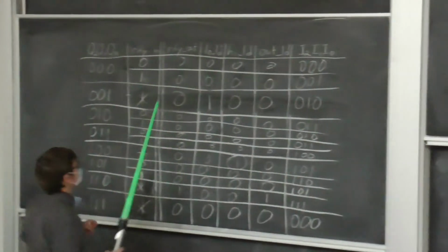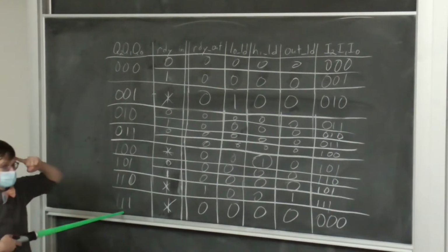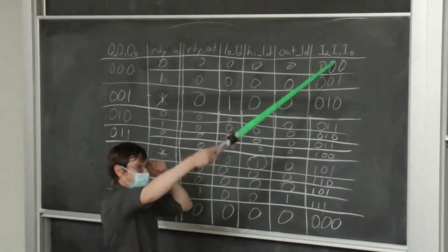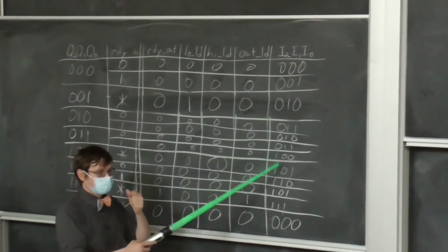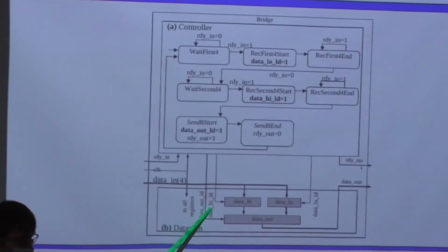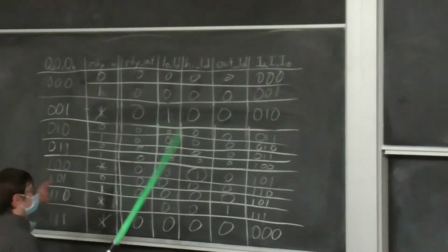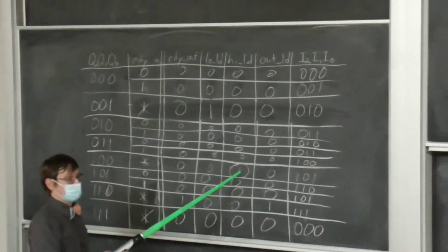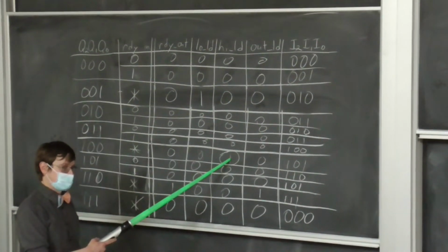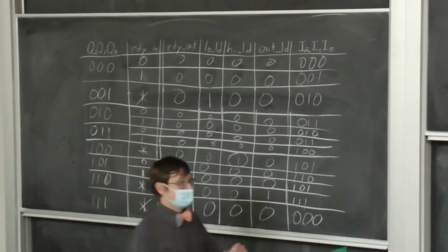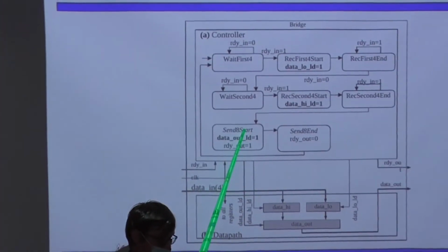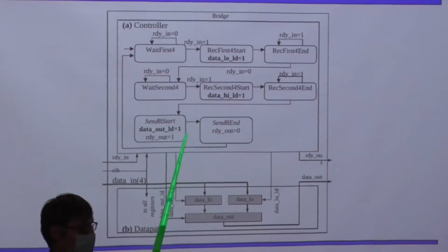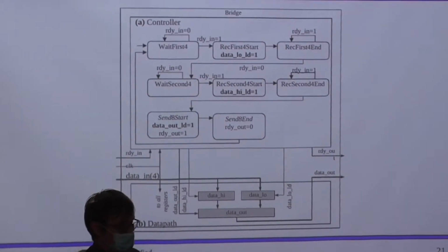So, essentially, interpret this as the current state column, interpret this as the next state column, interpret these binary numbers as decimal numbers if it helps you count, right? And basically all this is telling us is that in state 0, 1, 1, 0, 0, the high load signal needs to go high, otherwise it's 0. That's the information that we're deriving. It can be derived directly from the finite state machine diagram. Like nothing we have done on the board over there is not on this diagram, except where they've left information out, like here, where they didn't put ready equals 0, but we kind of assumed that it would be there anyway, right? Does that make sense?